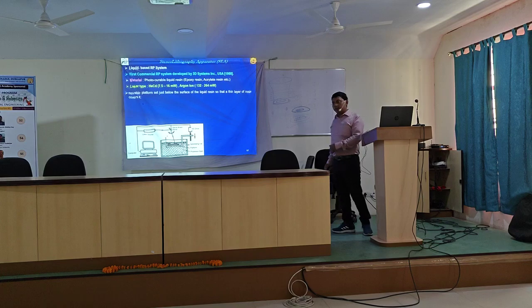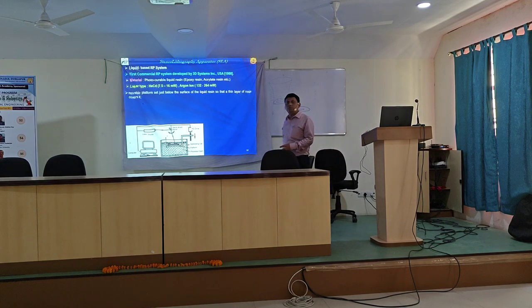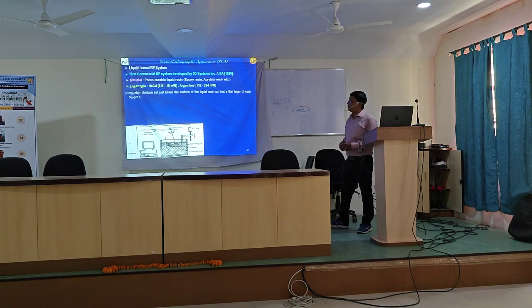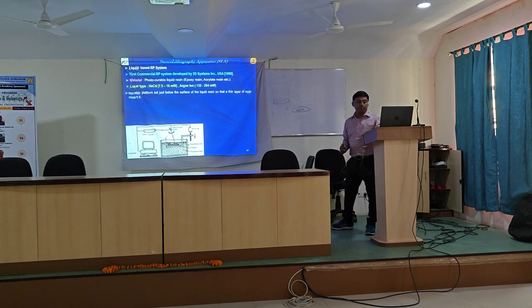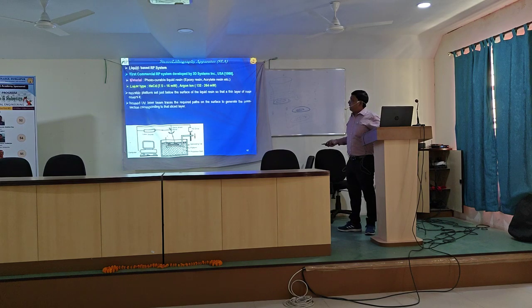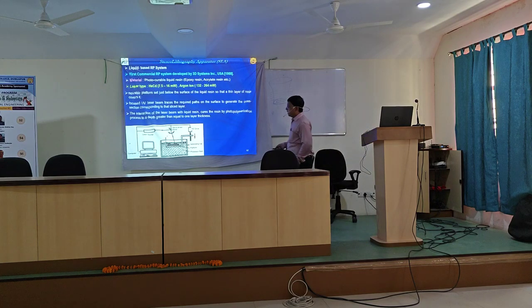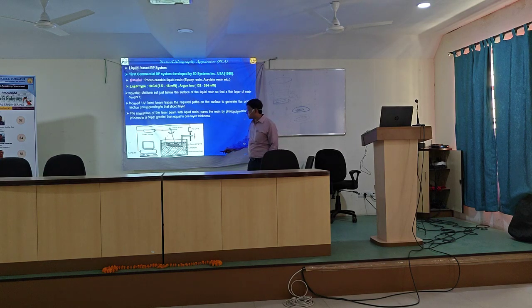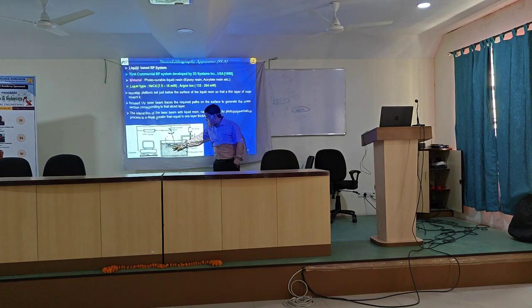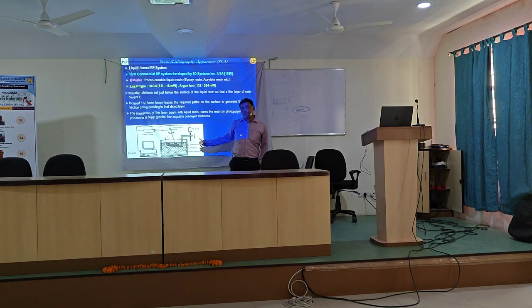In respect of additive manufacturing, the laser is very important. Without laser knowledge, it is very difficult to go into the detail of the additive manufacturing process. Now, in this particular process, after pre-processing, I would like to explain. Here it consists of a vat full of photocurable resin. The build platform initially will be here, and over that there is a thin layer of liquid resin.